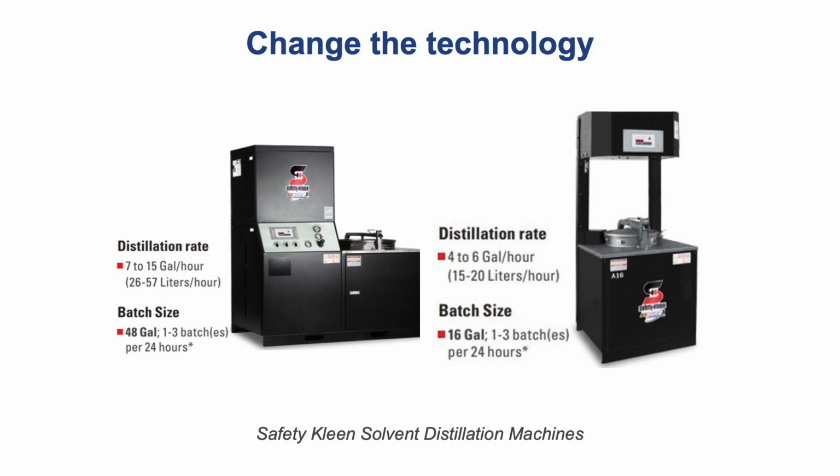These machines take used solvent and use a distillation process to separate the waste out and return the clean solvent. This process allows solvent to be recycled, which significantly reduces the amount of raw material that needs to be purchased and the amount of hazardous waste and air pollutants produced. One recent study of these recycling machines has shown an 80 to 90% return rate for recycled solvent. You may find similar results.